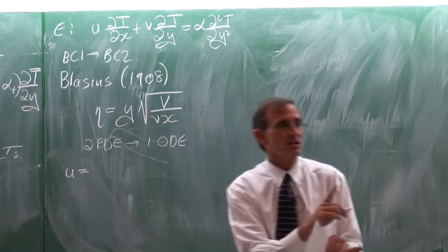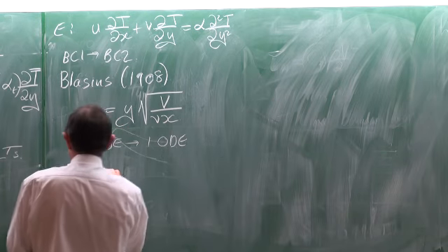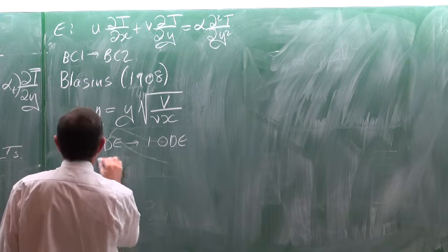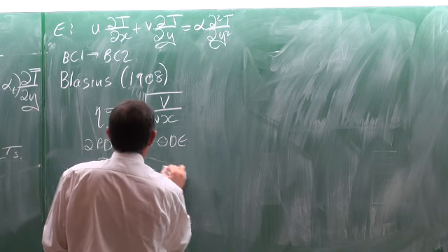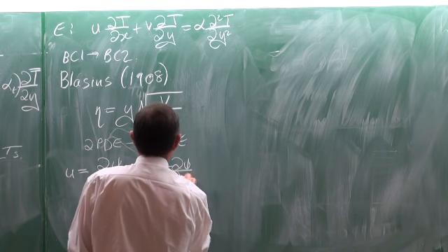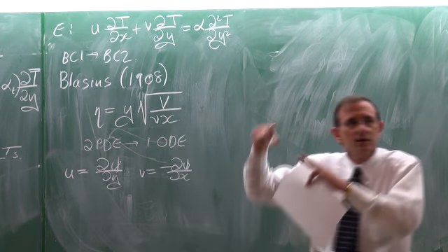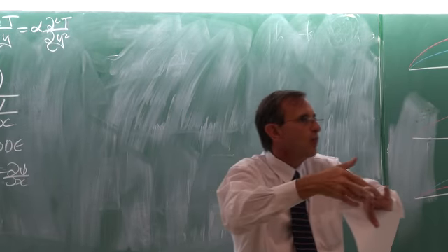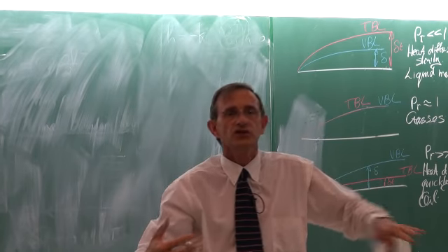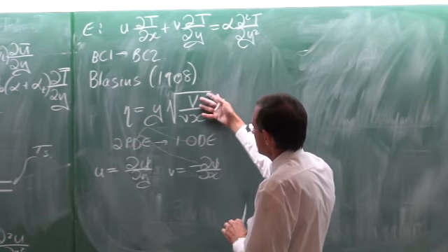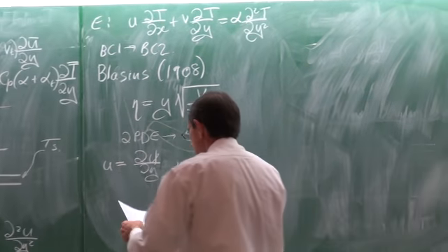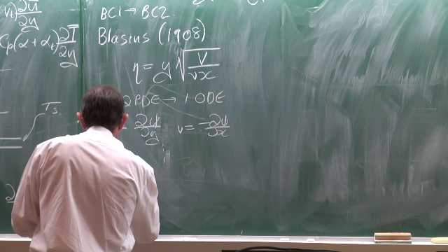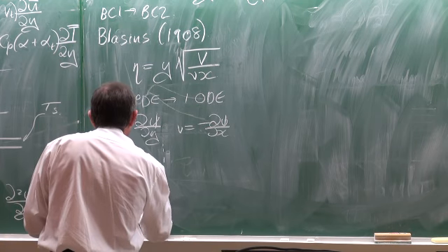You'll remember that we did the stream function where we said that u is equal to partial dψ/dy, and v is equal to minus partial dψ/dx. What is the psi? It is sort of the path a flow molecule would follow. That is the stream function. So we use this similarity variable and those two things, and I'm going to spare you all the mathematics. We're not going to do that in detail. The result was that he then developed a third order differential equation looking like this.